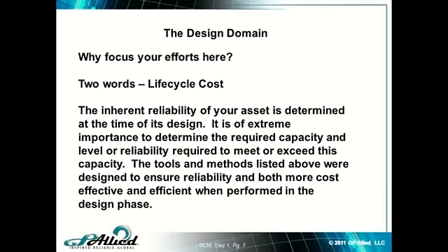So it's all about life cycle if we do a good job in the design. If we don't take our time and use these tools and elements, it's going to impact the overall life of the equipment and the cost it's going to take to maintain it. I often tell people in that design phase, you might want to think about designing it at 20% above what you're expected to first run at, right? Because if the product is good and customer demand goes up, it's only human nature to say, let's run it faster, let's get more out of it. So design for that to occur.